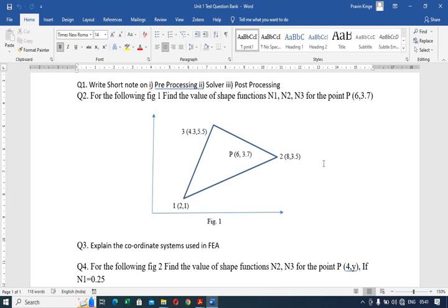One can go for any commercial software like ANSYS, Hypermesh, NX, or you can use open source software also for carrying out the analysis of simple components. So once you import this model into the analysis software, then you apply the material properties like Young's modulus, Poisson's ratio, density.